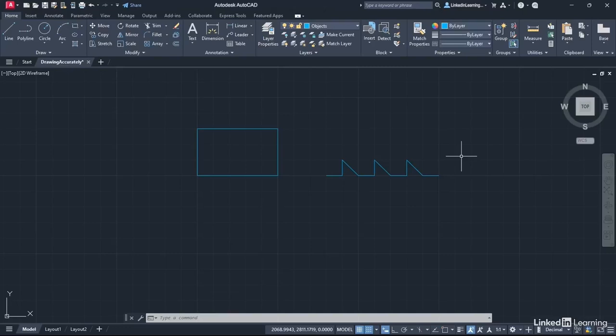Now, obviously, this is a fairly basic method of drafting, and it can create some basic shapes. Another typical one might be you've got flowcharts to draw. It's really useful if you use those regular shapes on the grid and snap to the grid to draw your flowchart symbols. There's a lot of ways and means of working with this, but you can use circles and arcs as well. So if I go to the circle command, let's do center radius. If I pick that intersection of the grids there and come out, can you see each grid square is making the radius bigger?